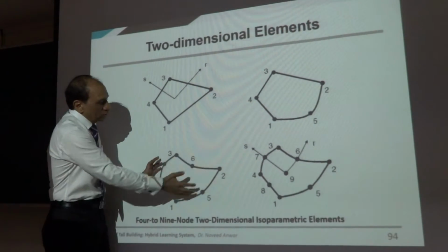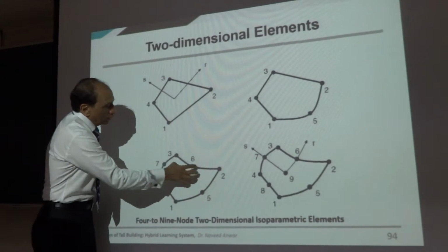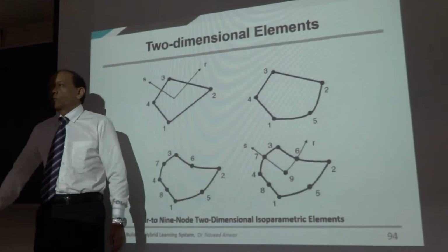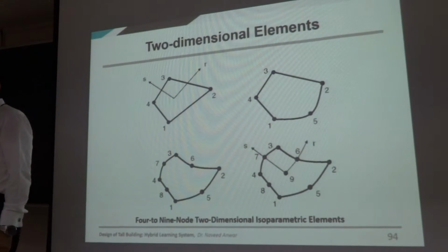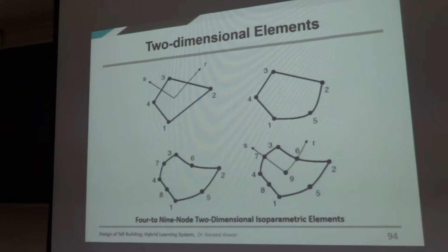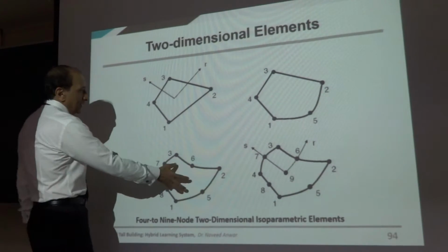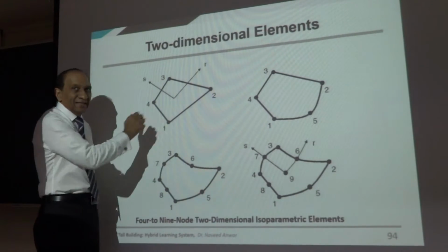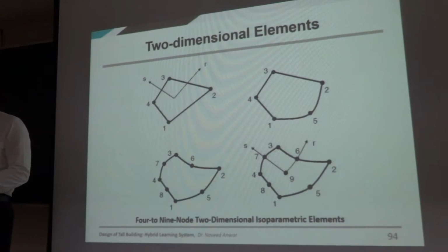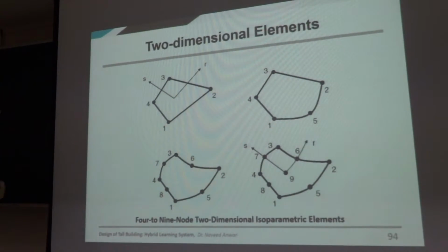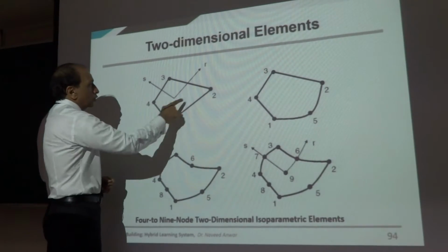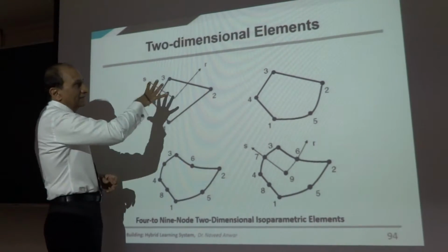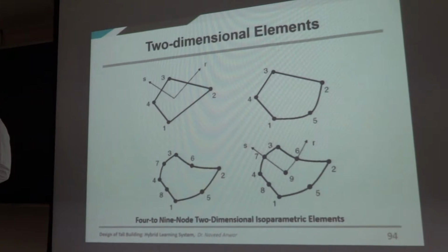So you want to do curve things, you divide it into 4. Instead of using 1 element, you use 4 of them. Model the same thing, right? Because computation-wise, this element and this one, 4 and this one, nearly the same now. So primarily we use now 4-node elements like this, and model almost everything by using 4 or 3-node elements.